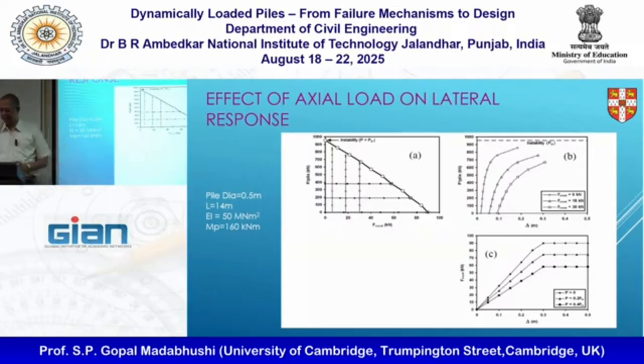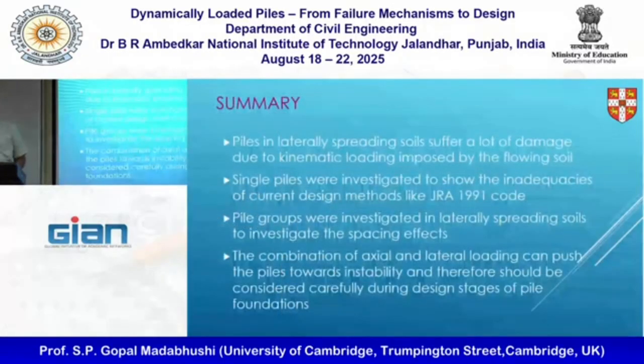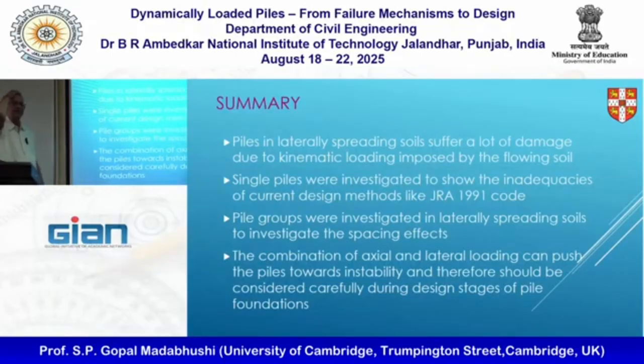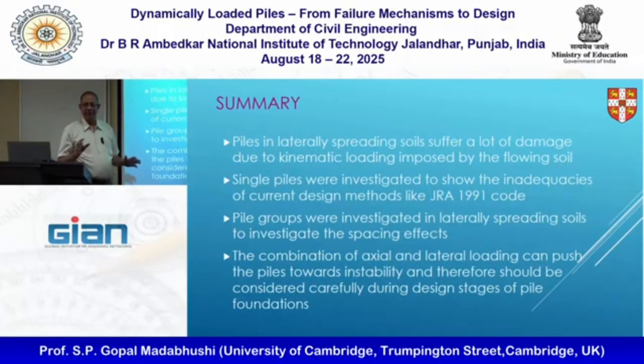Very good. So I'd like to summarize with this slide, where basically piles in laterally spreading soils suffer quite a lot of damage because of this kinematic loading imposed by the flowing soils. This is very clear. You've got inertial load, but you also have this kinematic load, which is where we started all this a few days ago.